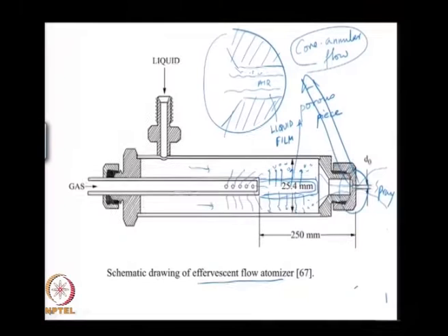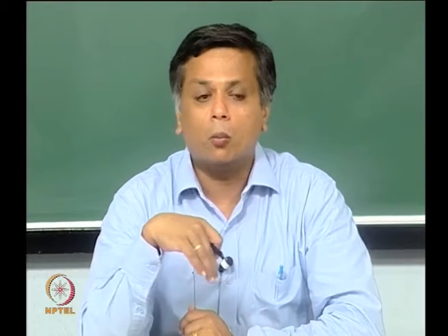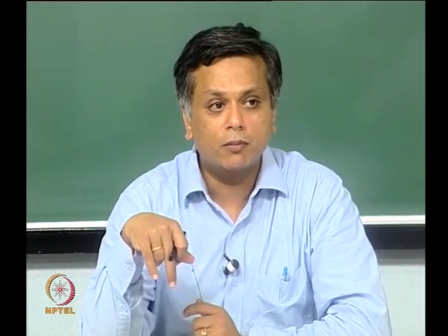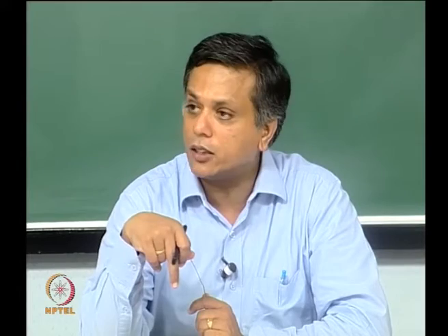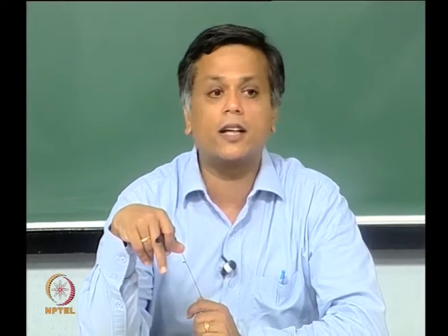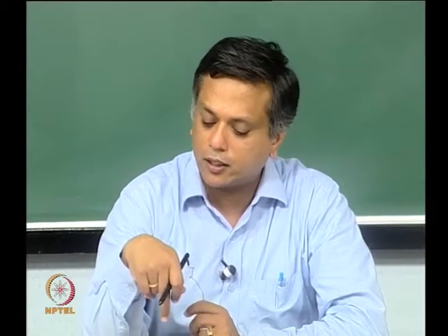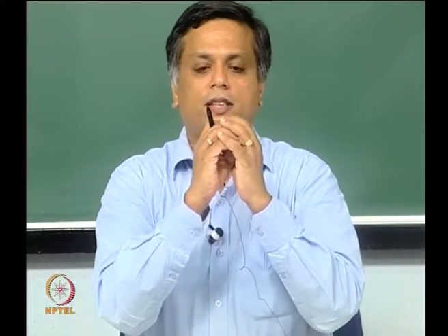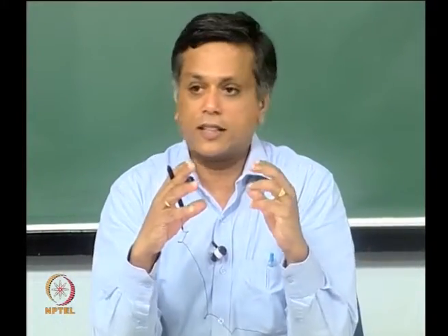you have created a spray system where the air and the liquid are internally mixed, and they are very intimately mixed, as a result giving you much more efficient transfer of momentum and energy between the air and the liquid. Because the air could be at a slightly higher pressure, the air and the liquid coming in contact gives rise to this expansion of the air, and that is essentially what gives rise to atomization. What is the energy source for atomization in this particular design?